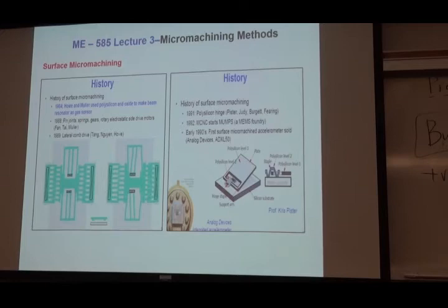These are typically about 2-3 micron deep, but they support that. And then the proof mass is going to be attached to the anchor through beams, right? Because the stiffness is going to come from the beams. So if you make the beams very, very stiff, then you need a larger force to move the accelerometer. If you want to detect lower frequencies, then you make the beams compliant, less stiff, right? That's what you were supposed to cover in mechanics of solids and so on.